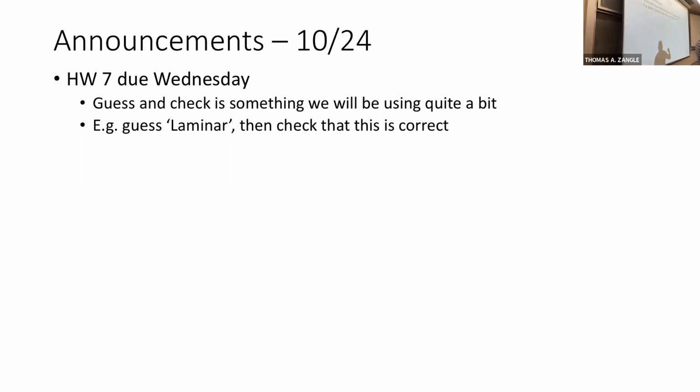And at the start of the problem, you don't know whether or not the flow is laminar. So how do you get started? Well, you have to start someplace. So you have to make a guess, and then at the end of it, check that your guess was correct. In this case, that means guessing that the flow is laminar, because that's all we've covered so far. And then computing the problem as usual, and then at the end of it, checking whether or not the flow was in fact laminar flow, right? So check your Reynolds number, make sure the flow is actually laminar flow.